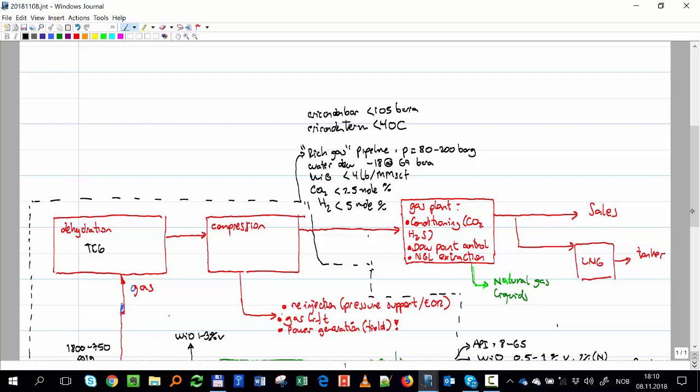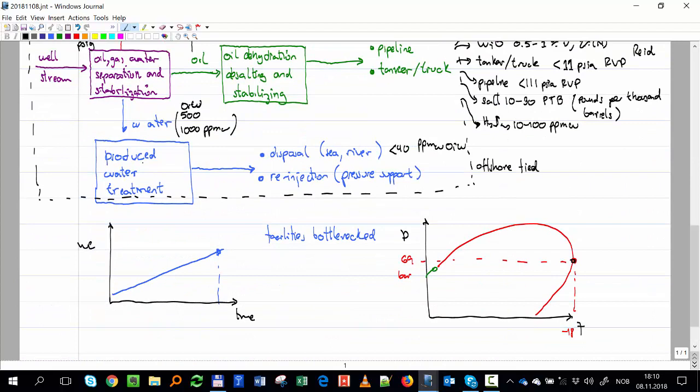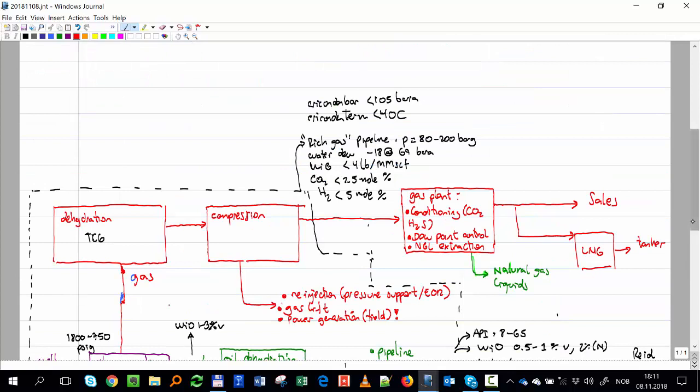Okay, and that basically is another way. Here on the dew point, I'm specifying it has to be below that, but it can be that my envelope, for some reason, is doing something like this. Therefore, I use the cricondentherm and the cricondenbar just to limit the size of my envelope, such that in the transportation process in the pipe, when I change pressure and temperature, I ensure that under no conditions I will have a significant amount of condensation from the gas.